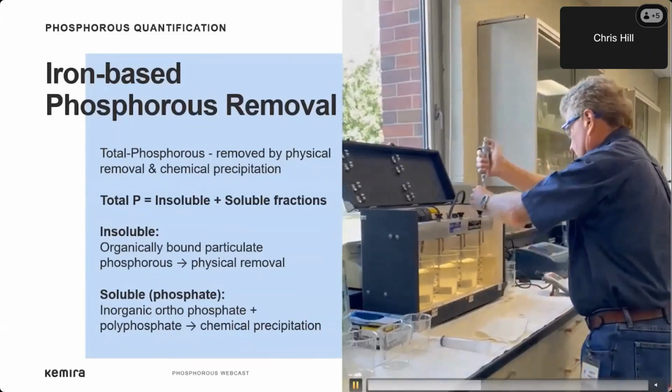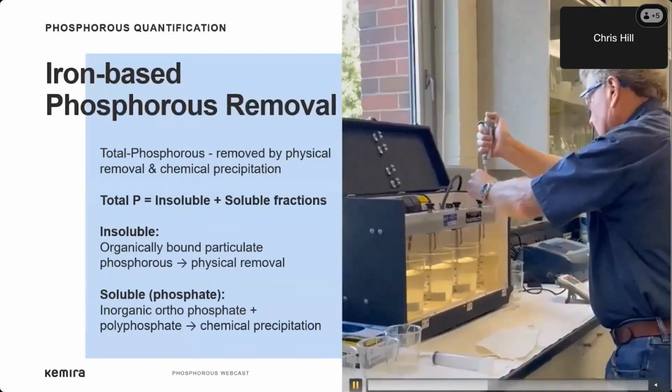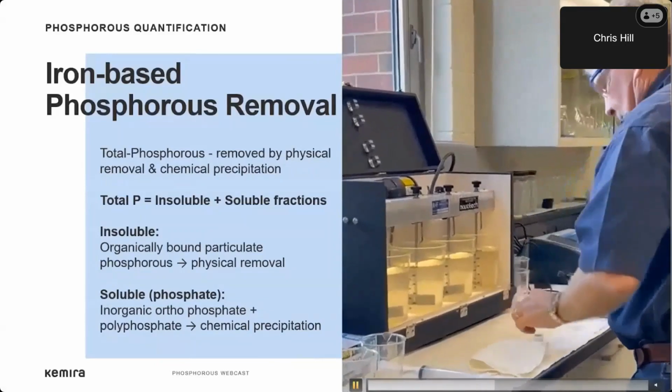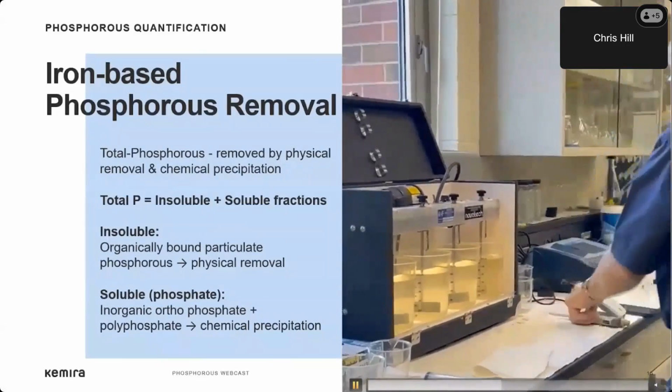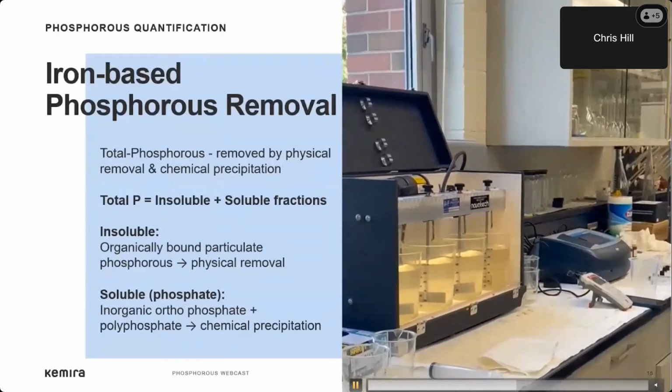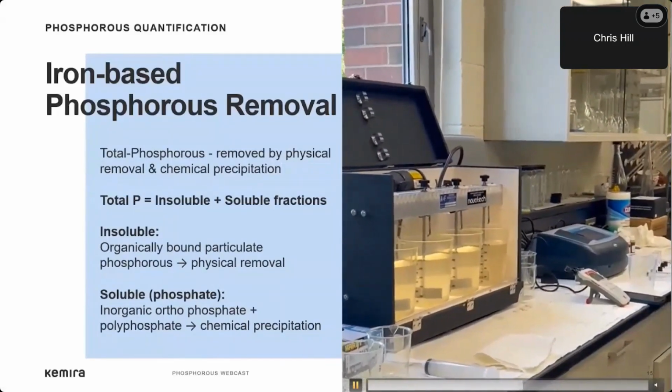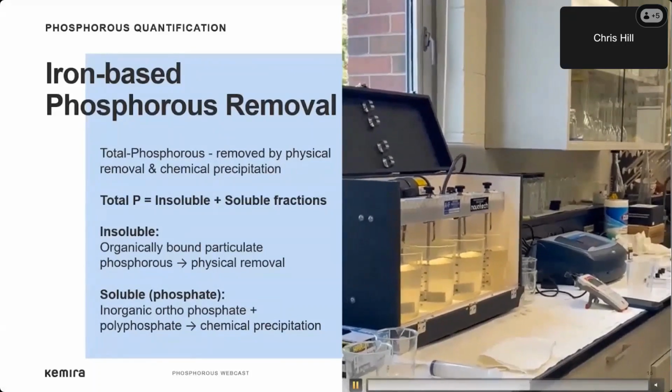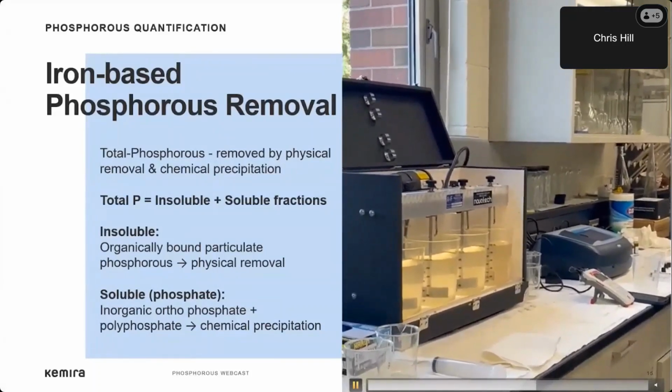Phosphorus can be removed with up to 90+% efficiency, causing the final phosphorus concentration to be lower than 0.5 milligrams per liter and as low as 0.1 milligrams per liter. Now I'm handing it over to Ricardo, who will tell you more about coagulant addition points and dosing.